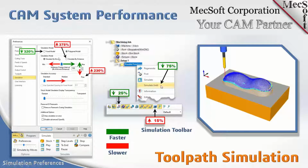If you pick simulate by moves, that's the fastest. If you look down here on the simulate tab, there's a checkbox for simulate by moves. Using the default parameters, check to simulate by moves, and that will be faster. Then you also have a slider here, and that relates to this slider down here on the dialog.